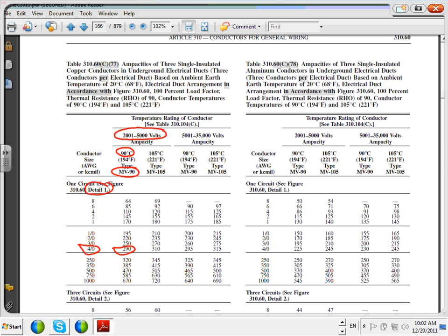So what we're going to write, you need the 3 conductors, number 4/0 MV-90. Instead of THHN, this is a medium voltage conductor, fully shielded medium voltage conductor. MV-90, 90 stands for the insulation rated for 90 degrees, so they can get as hot as 90 before smoke starts coming out of it. Unlike low voltage, where we size based on 75 maximum. This is a very major change. I will get back to this in detail as we go industrial, guys.